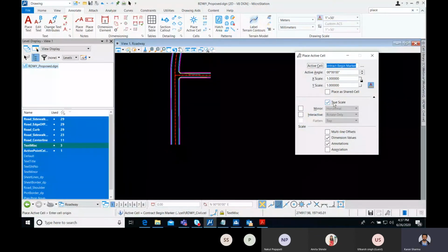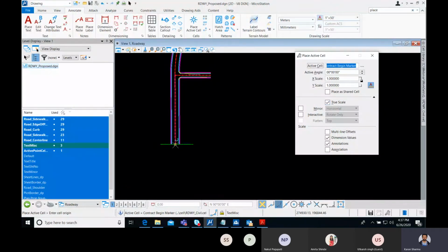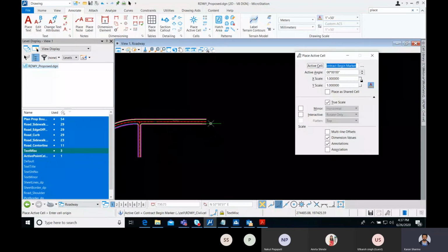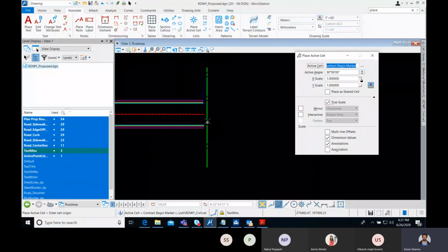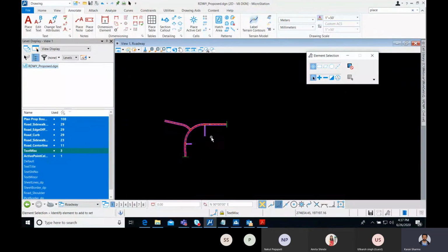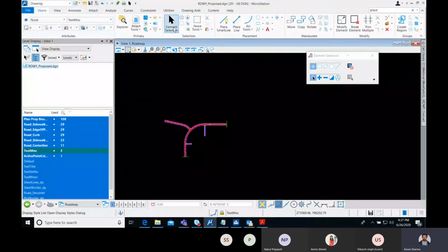My true scale is on, as I discussed before. Also my annotation scale, I'll put this one here. Okay, and one more I need to put here. No need to, we can just change its rotation from here, maybe to 90 degrees, and put it here. That's it, simple. Okay, now I'll attach a reference here, some terrain.